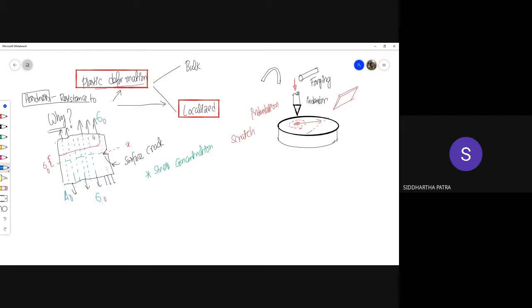Now, if I keep on doing so, obviously in the region of the crack, there is not enough material available. So once you get closer to the crack tip, these regions try to make a certain curvature. If you are a bit far from the crack tip, this curvature diminishes, and if you're really far from the crack tip, this curvature essentially vanishes.